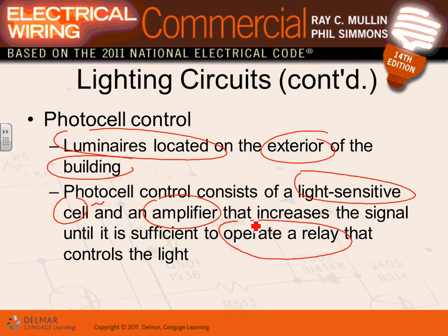So here's how it goes. First you sense, then you amplify the current, then the amplified current will operate the relay. The minute you operate the relay, it will drive. Here's a relay contact. The relay is getting a signal from the photocell, and the photocell will drive this contact to close. Any comments, any questions?